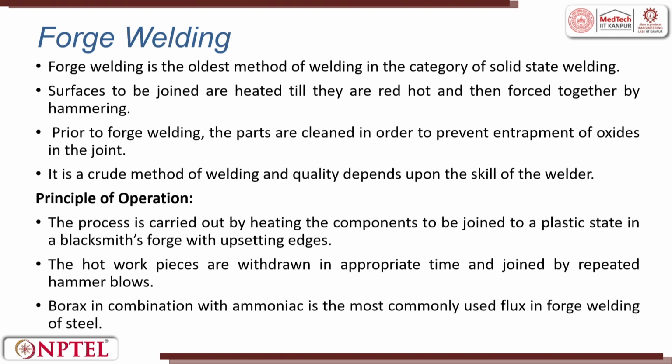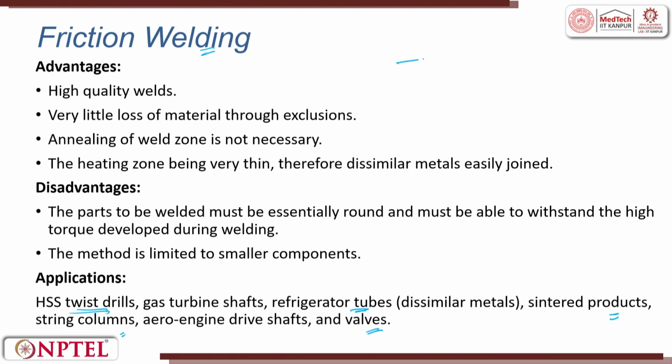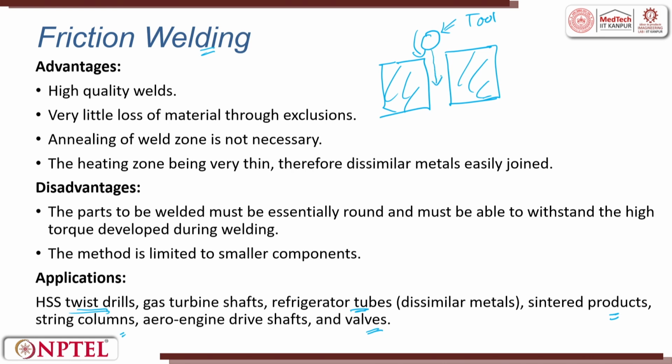Interestingly, in friction welding you can also have two plates here, right, and then you can have a tool. I am drawing the plan view, this is workpiece, this is workpiece, it can be similar or dissimilar. Here is a tool. So, the tool rotates and then it is moved inside the two metals. Now this rotating tool creates a friction between these two plates, and then you try to have a joining. Here is the joining. This is called friction stir welding process.